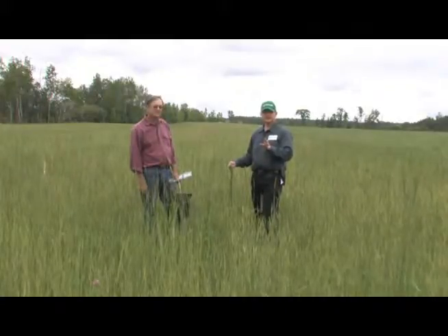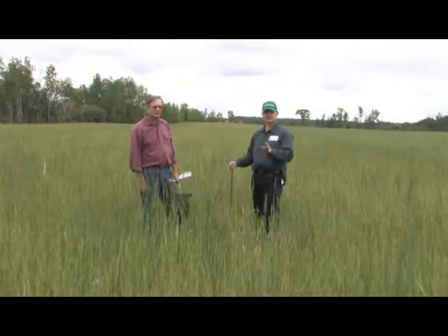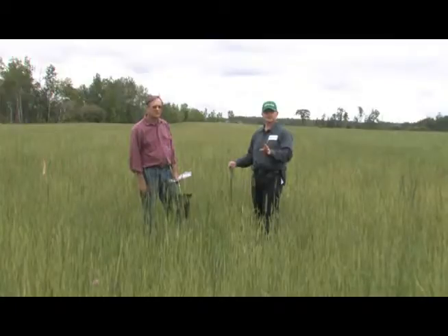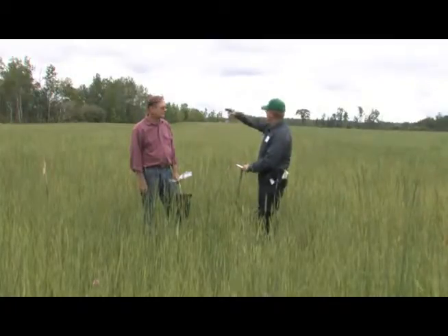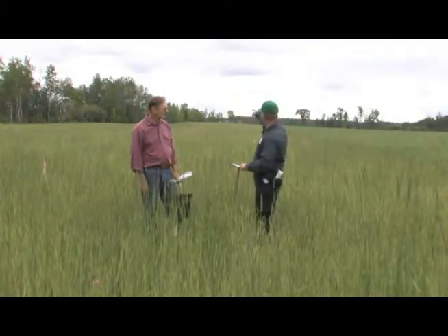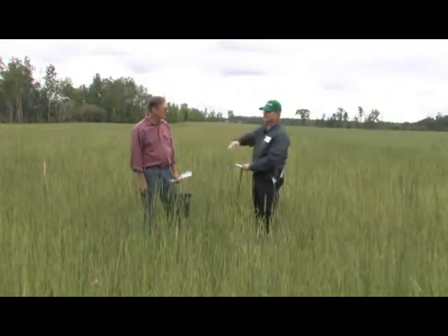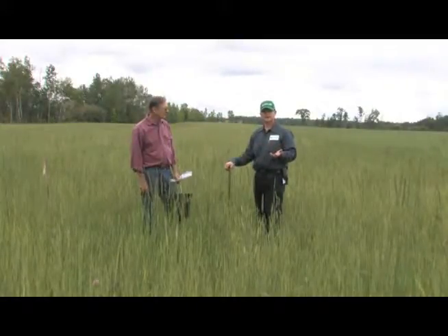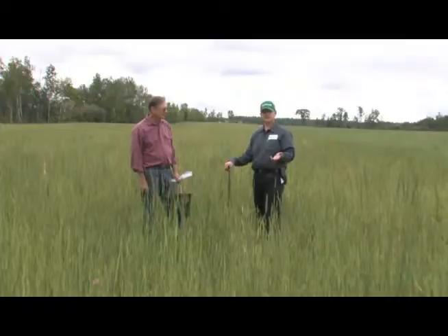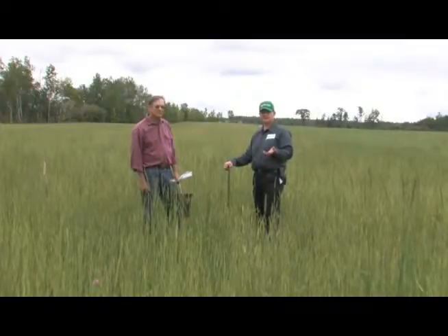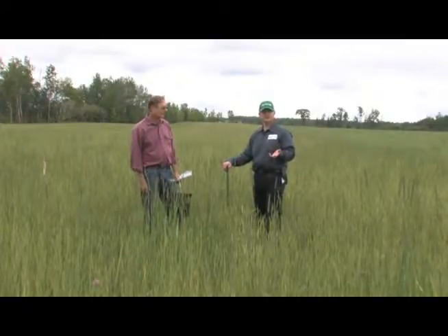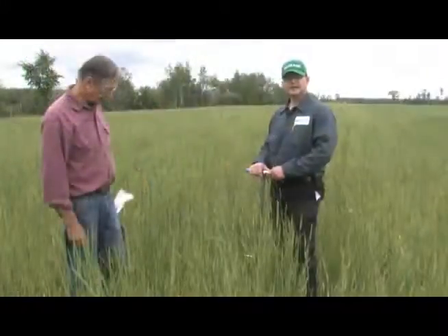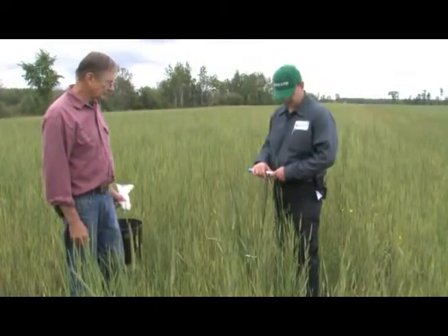And then also you want to avoid any real changes in topography. You may need another soil sample for that area. And then of course you want to avoid the wooded areas that are around the field as well. Other things to avoid are manure piles, chemical spill areas, and then also areas in which there were farm buildings at one time. Obtaining the soil sample is quite straightforward.